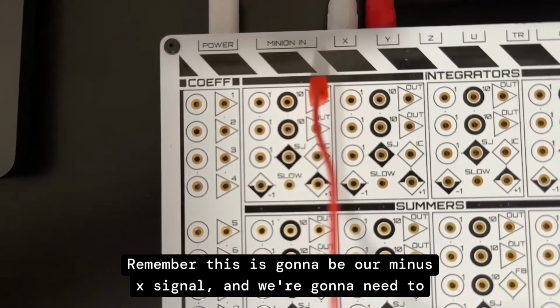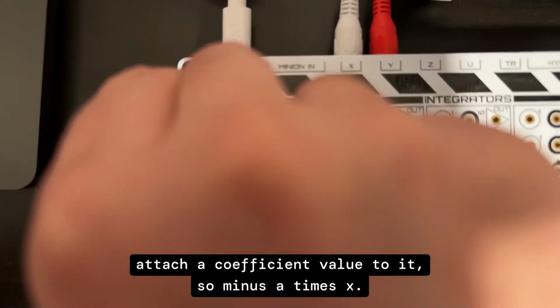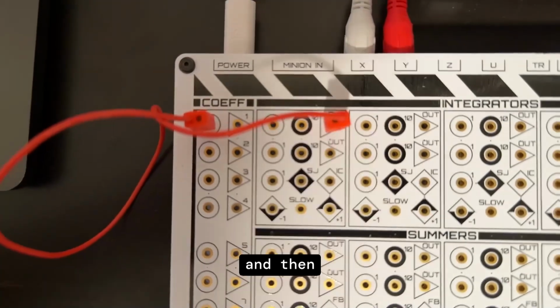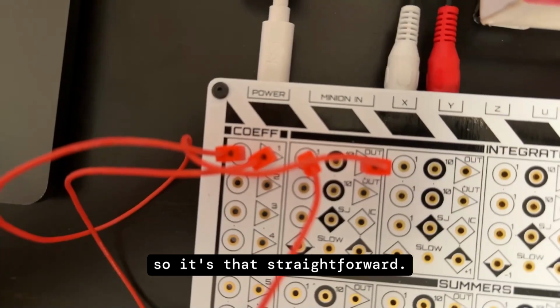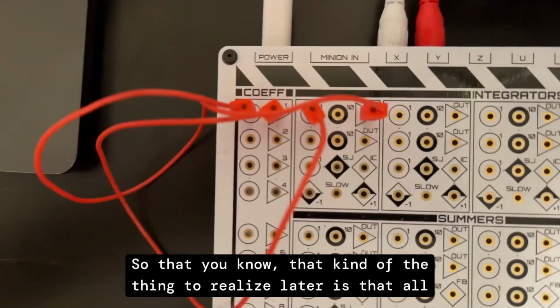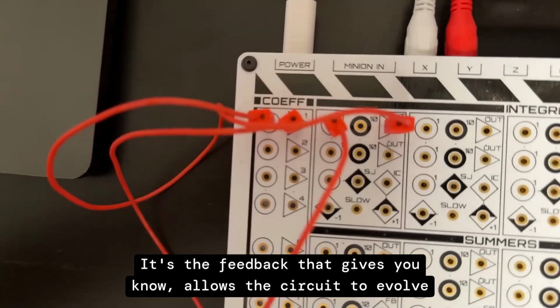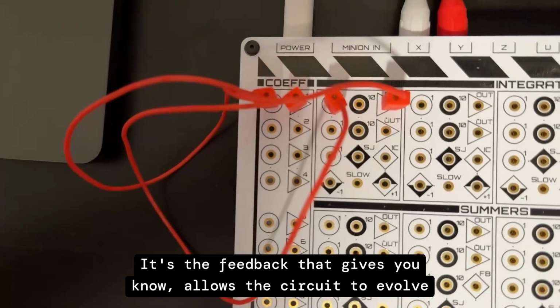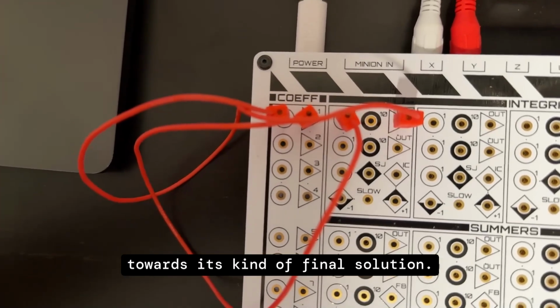So we have some output here. Remember, this is going to be our minus x signal, and we're going to need to attach a coefficient value to it, so minus a times x. This will be coefficient 1, and that becomes our circuit. It's that straightforward, a very simple circuit. It's closed, and the thing to realize later is that all your integrations have to be closed. It's the feedback that allows the circuit to evolve towards its final solution.